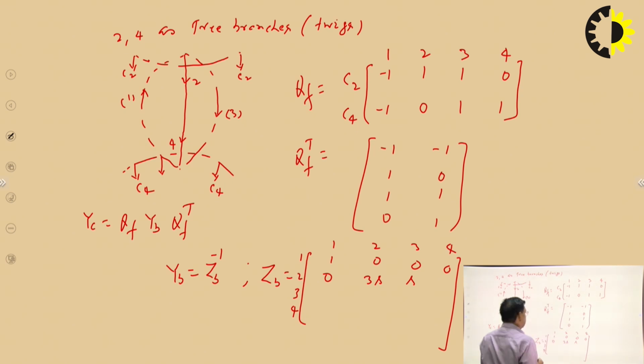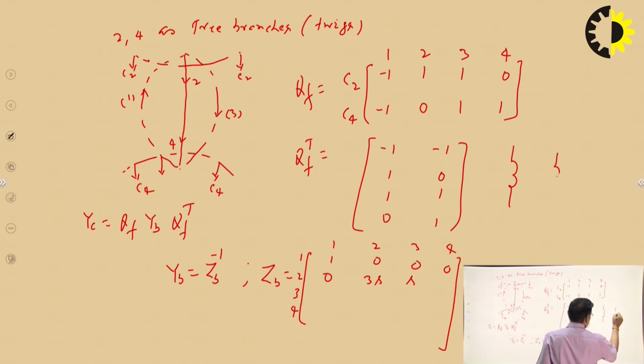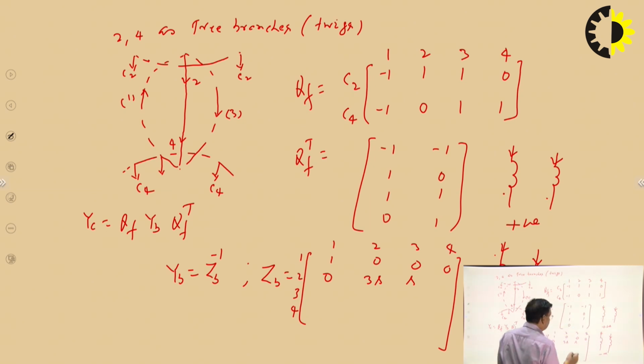Okay. Now one more question, whether this will be a plus sign or a minus sign. Suppose there are two windings, and here is the dot, and current is leaving in both the coils, so the flux direction will be positive. Suppose it is like this and like this, and current is entering in this coil and leaving in this coil, so it is minus. This way we can take the direction of the mutual inductance.